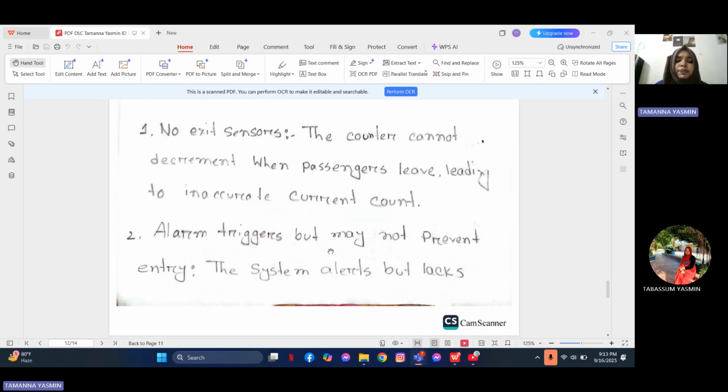Second, it relies on perfect RFID readers. In reality, signals can be blocked or missed, leading to incorrect counts. Third, the alarm logic is too simple. It assumes people will walk in a perfect single file. A group of 3 walking closely together might accidentally trigger a fourth sensor, causing a false alarm. Also, using a simple DAC to send data to a control room is prone to noise and signal degradation over long distances. A digital communication method would be better for this.